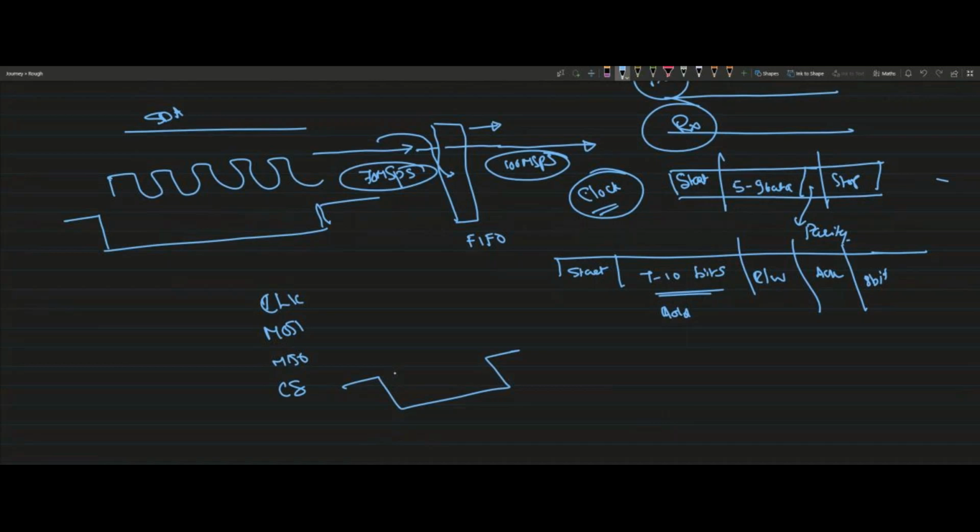So what are the advantages and disadvantages of these protocols? You now have all three protocols. Based on our observation, can you tell me the advantages and disadvantages? Maximum speed for SPI is like 10 megabits per second. Can I go with that speed in UART? No, right? Asynchronous protocols do not support faster speeds. What about I2C? I2C is also slightly lower speed.